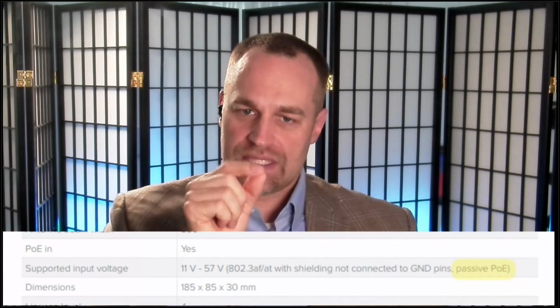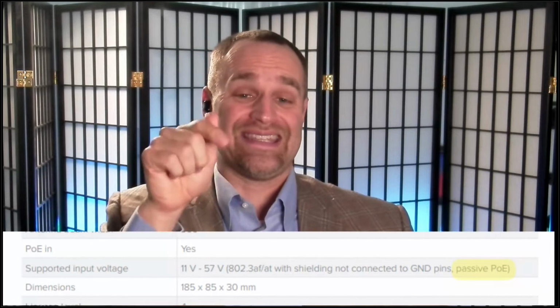When you see that on a specification or a camera, when it says 12 volt PoE, what it means is the camera accepts 12 volt DC if you plugged it in directly to DC power. But it requires 48 to 56 volt PoE if you plug it in through PoE. I know that's a little bit confusing, and some people call us up saying, hey, my camera specifically states I need 12 volt PoE. That's what the specification states.